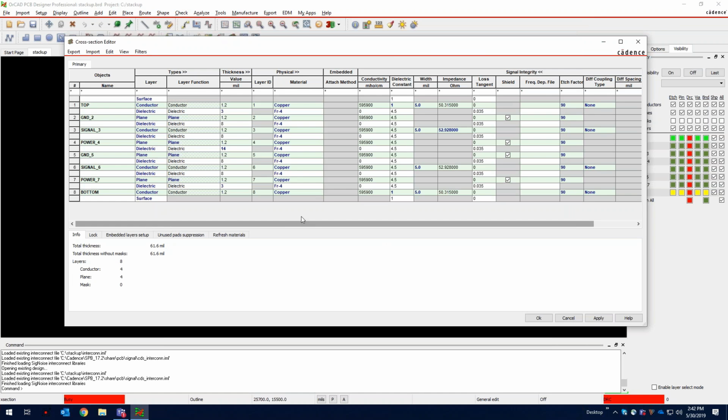So in this Stackup, you can see that the impedance on each of the layers is close to 50 ohms, which might be what you're looking for, but impedance shouldn't be the only consideration when designing the Stackup. There are also signal integrity and power integrity concerns that may need to be addressed. So when designing the multi-layer board, ask yourself the following 5 questions that Matthew had mentioned. First, are the signal layers adjacent to the planes? In this Stackup, you can see that the outer layers have a plane next to them, and the internal layers are embedded between the reference layers.